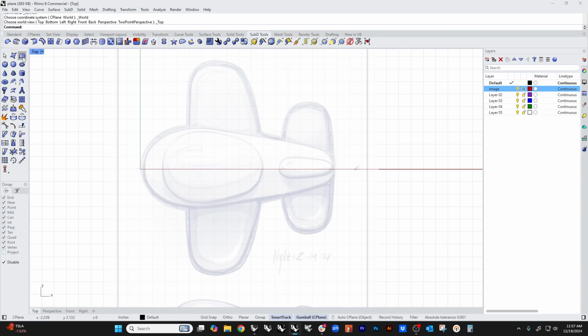Let's start with a single SubD plane, and we're going to set our X and Y count to 1, and do this from the center. I'm just going to stab that at 0 and pull that out to about the approximate width of the plane. Now, if you're in smooth mode, you'll notice that nice square just turned into a kind of ovally rectangle. Just hit the tab key and it'll go back to being a square.